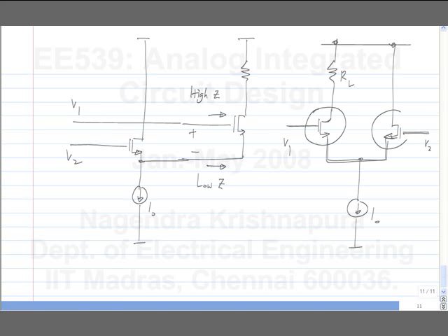Okay. Now if you look at it, if you look below this line, the circuit is entirely symmetrical, right? So in fact, I can think of this as the common source amplifier which is driven by this one also. I can put the resistance here and make it fully symmetrical, and I can either say that I am driving the left one with the buffered version of the right one, or the right one with the buffered version of the left one. So this is one way of arriving at the differential pair.